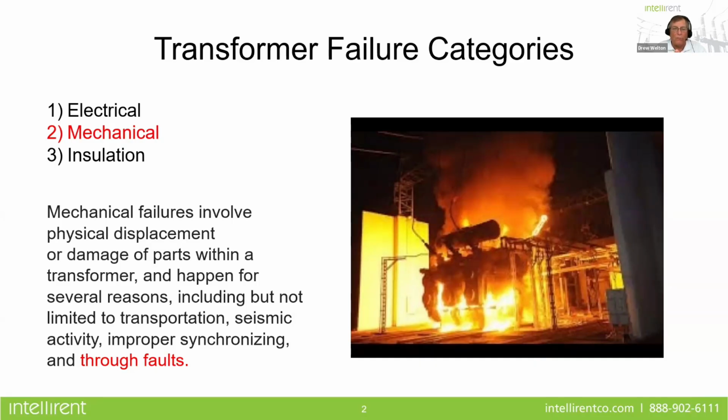And probably the one we're most familiar with is transportation. When you purchase a new transformer, and especially if it's a large transformer and has to travel by rail or flatbed, it gets subjected to certain shock and vibrations. And this is, of course, one reason why we put vibration monitors on new transformers, especially if it's going by rail, where they're coupling and decoupling rail cars all the time, and it can certainly cause enough vibration on the transformer, enough shock to actually damage the internal windings of the transformer. But you have other causes as well.